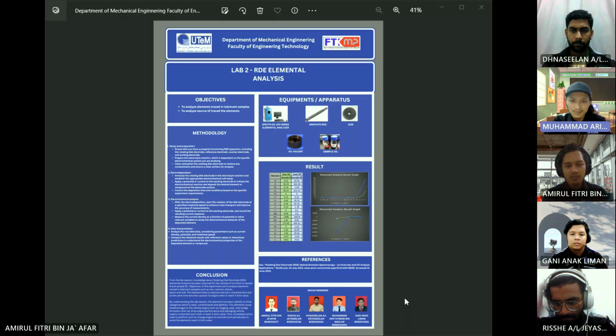Aluminium is detected in both samples, but the concentration varies considerably. The new oil sample B shows a concentration of 0.32 ppm, while the used oil sample B1 has a significantly higher concentration of 10.93 ppm. The elevated level of aluminium in the used oil could suggest contamination from external sources or potential wear of aluminium-based